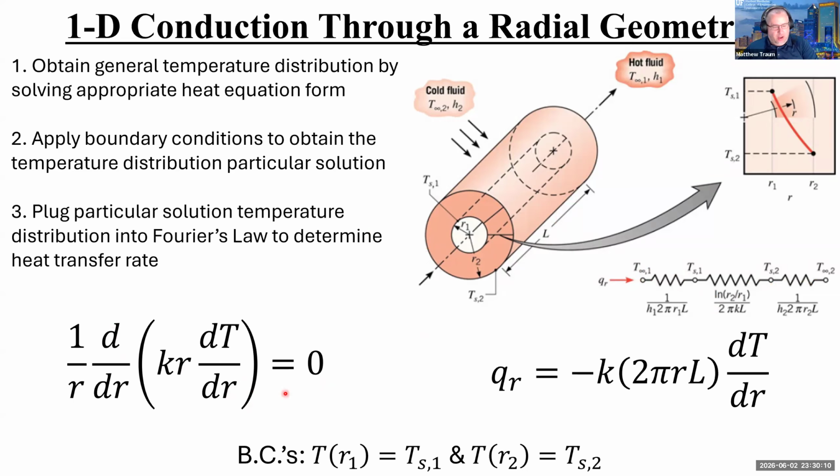my, so if we go all the way back, this is Poisson's equation, right? But it's Poisson's equation in cylindrical coordinates as opposed to in XYZ Euclidean coordinates, right? So notice a little bit of weirdness. This is what I mentioned in the previous lecture. I've got R, which is sitting inside this derivative. And then because the units have to work out, the units have to be temperature per distance squared, I've also got an R sitting in the denominator out here so that at least in terms of units, this R and this R cancel each other.